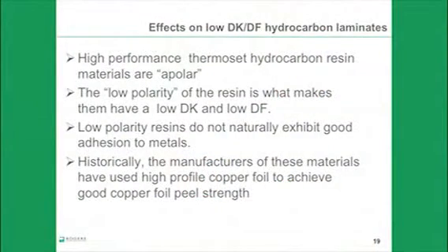Now, how this all fits in with RO4000: all high-performance thermoset hydrocarbon materials are apolar, if you were paying attention in freshman chemistry, and it's this low polarity of the resin that gives them low dielectric constant and low dissipation factor. The downside is that low polarity resins do not naturally exhibit good adhesion to metals, so historically manufacturers of these materials have used high profile copper foil to achieve good copper peel strengths.